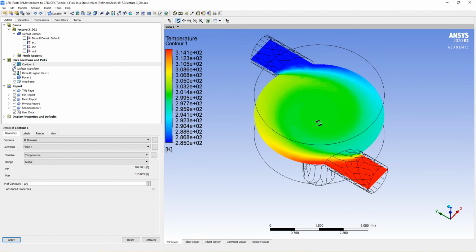Okay, so sometimes this is something that you're going to have to keep in mind: maybe my inlet and boundary conditions are correct, maybe I measured them correctly, or I extracted them from literature correctly, and what I need to change is going to be either the geometry or the mesh, or something related to your solver controls. Okay, so this is something that you need to keep in mind.